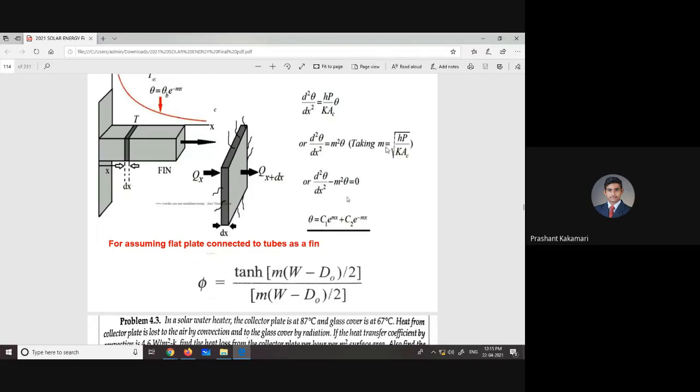to make it a small value, they have taken m. So that m value, if you analyze, it is multiplication of convective heat transfer coefficient h between pin fin and air. P is the perimeter of this surface, perimeter of the pin fin itself. So for small area, they have taken this perimeter. This perimeter is analyzed here or zoomed here. So for the entire pin fin, if you take, it depends on the rectangle surface, circular surface, or square surface, whatever, that perimeter they have considered, divided by conductivity of this pin fin material, maybe aluminum, copper, like that.